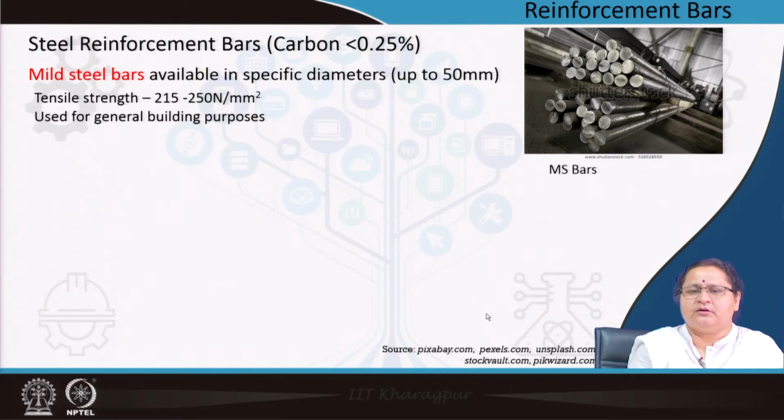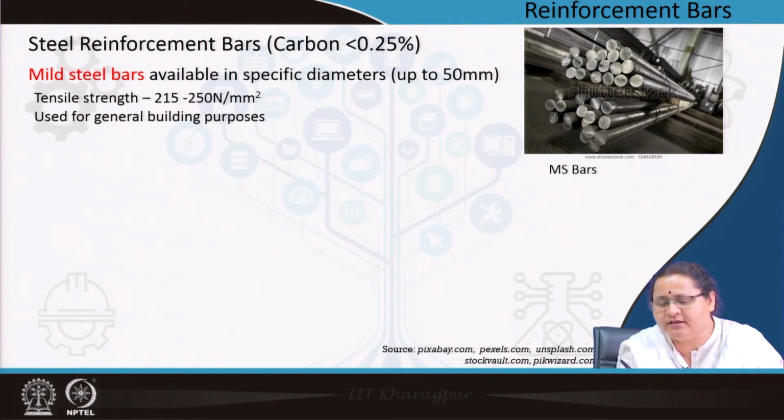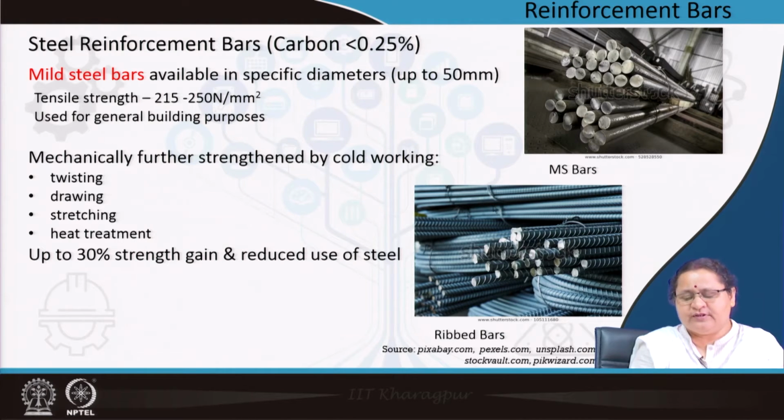And to be precise, there are grade 1, grade 2, different types of mild steel bars. As you can understand, mild steel bars are plain on the cross section. If you see the picture carefully, it has a smooth surface on its longer face. Unlike the bars which you see in this new picture, here you see ribs or lugs. These are called cold twisted deformed bars or high yield strength deformed bars.